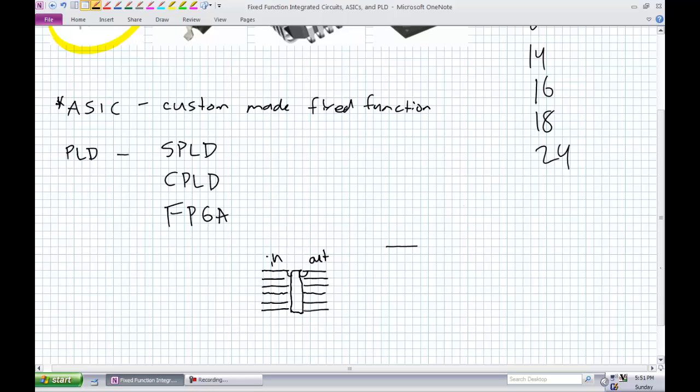It would make no sense whatsoever if I took that device and electrically connected pin 1 to pin 12. I don't put them in the same column. It's not going to work, because 1 and 12 have to be separated. They have to be electrically disconnected from each other.